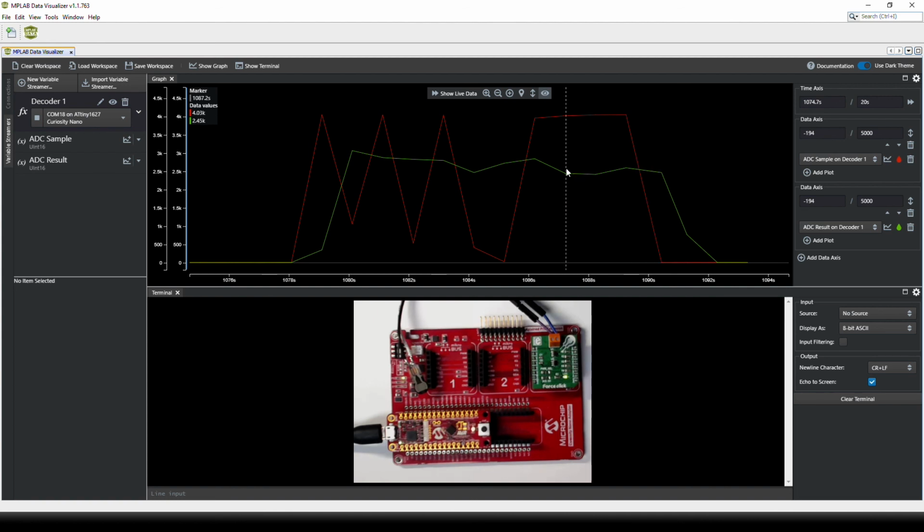And that is because our results are too slow and we are averaging away the changes, which means that if the result frequency is too low compared to the frequency of the signal we want to capture, we will lose information and not be able to recreate it properly.